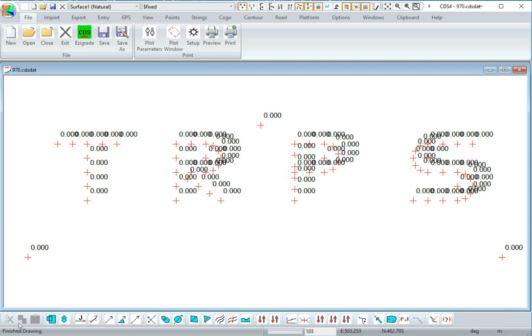Now there's also some more shortcut items along the bottom here, and at the far bottom, the status bar. Now that's the next available point number, and that's your easting and northing when you move your cursor around. So I'll move my cursor up onto the screen and move it, and you can see they change. And here we're displaying degrees and the job's in meters.